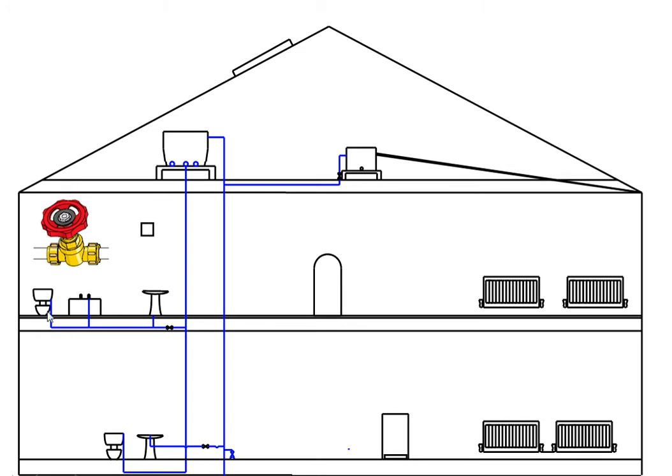The size of these, you have 22 to your bath and to your sink and your toilet there 15mm. And then we have our cold water supply coming down here to our shower, which is an electric shower, so that heats the water by an electrical element.